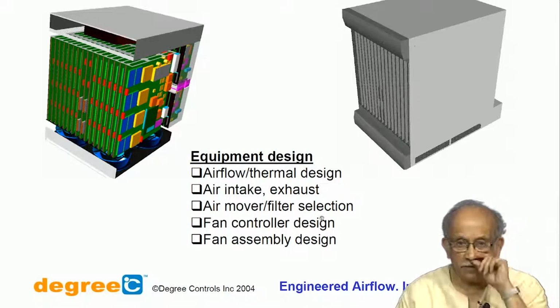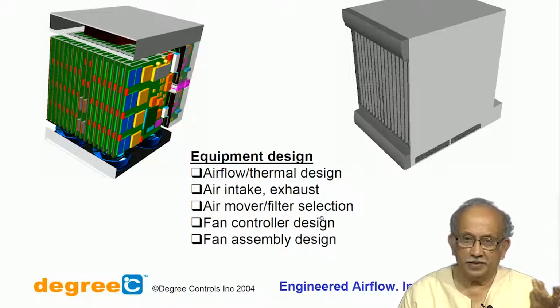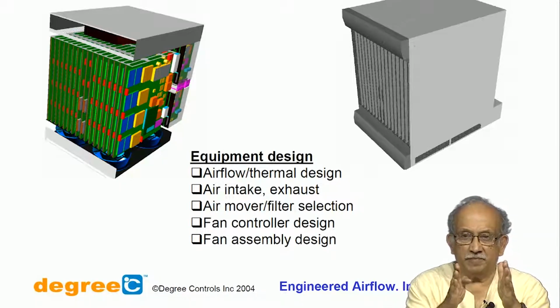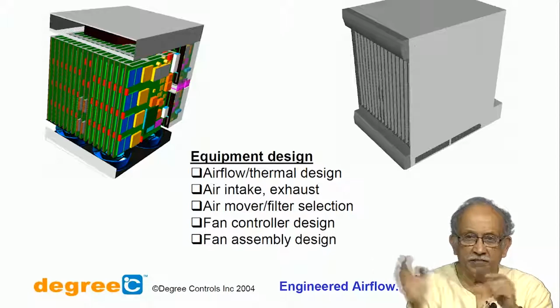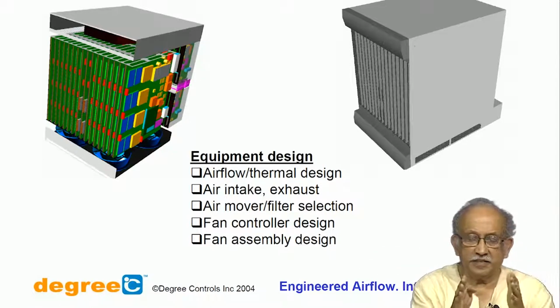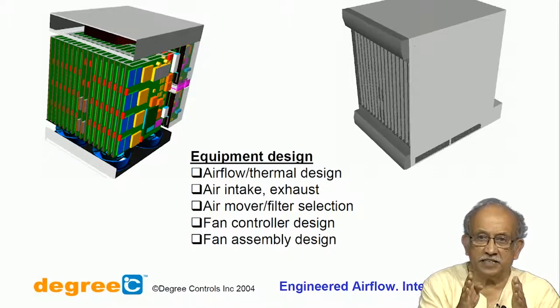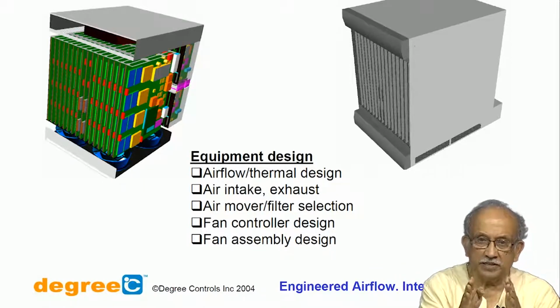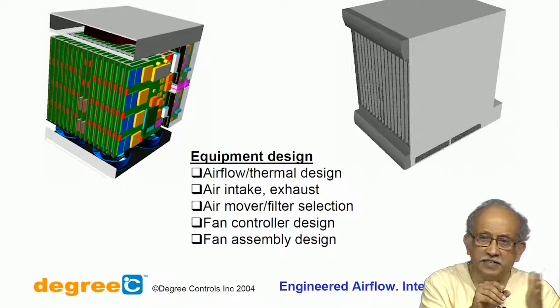But filters are now about as sophisticated as anybody else. So, one of them is you have a cascaded filter. From my point from the right side, let us say that the air is coming in and here it is exhausting itself. A cascading filter typically has a coarse filter on the air inlet side, in between the body of the filter is there, and the last is the fine filter.